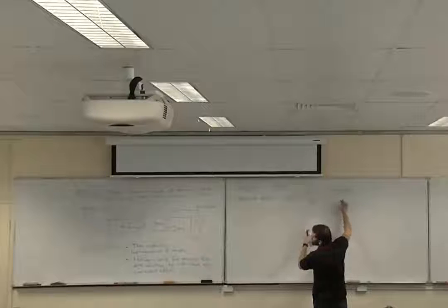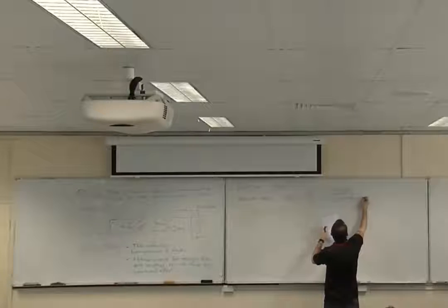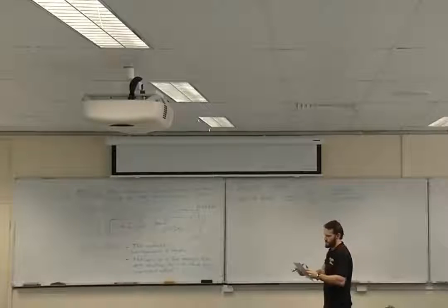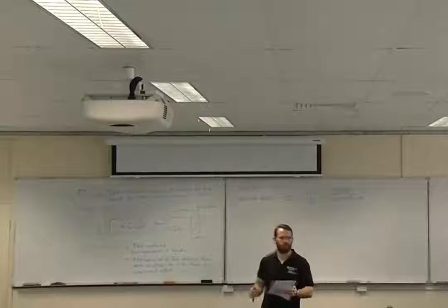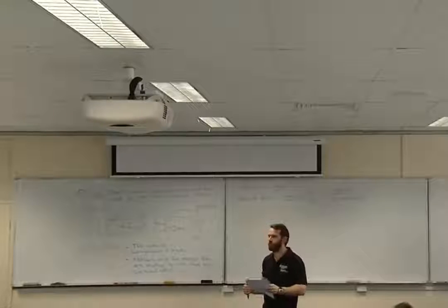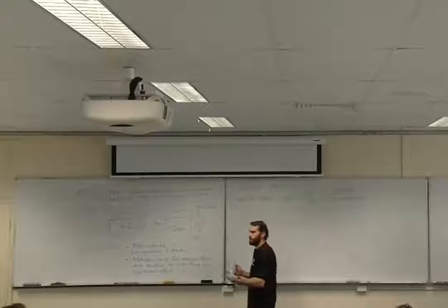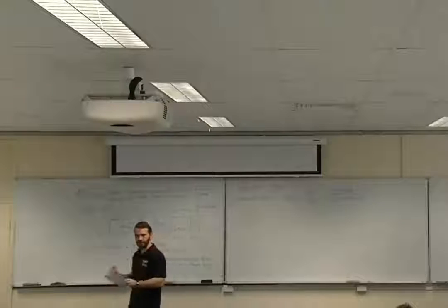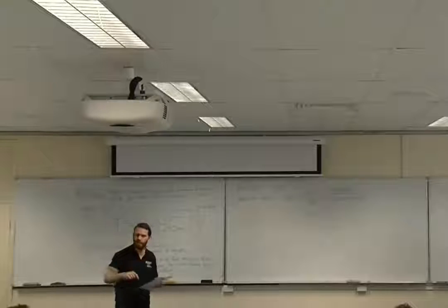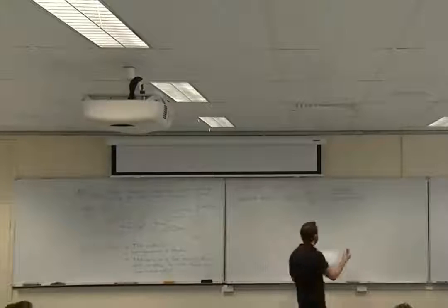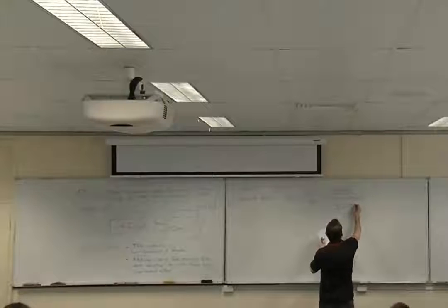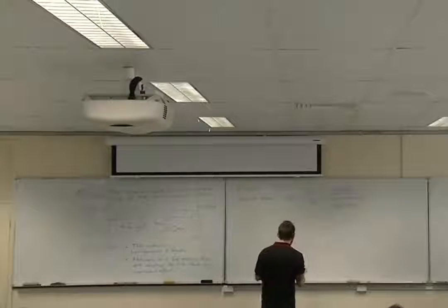What we should do is write in meters: 0.1 minus 0.05, times 0.025. So what do you get for nominal stress? That's the area you use for the actual value of normal stress. 36 megapascals, or 36 by 10 to the 6 pascals, whichever.